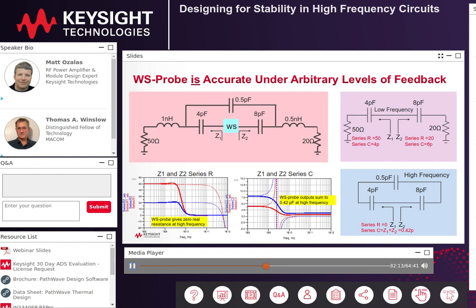The high frequency asymptotic behavior of the circuit looks completely different. The inductors become very high impedances, and from the probe's perspective, we see a loop formed by 3 series capacitors, where the half pF capacitor is now closing the feedback around the loop. At high frequencies, there are no resistances within the loop, just the 3 capacitors, because the 2 external inductors outside of that loop become very high impedances.